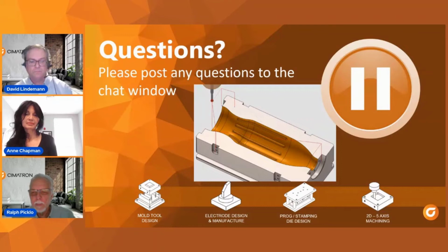Now, another one from Tim. You mentioned using cutter comp when it is measured. When it measures the part before doing the final cut, will it make the adjustments in the program itself, or will it adjust the wear offset in the tool table? Yes, it's going to adjust the wear offset in the tool table.